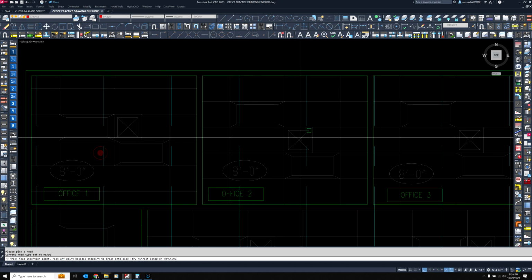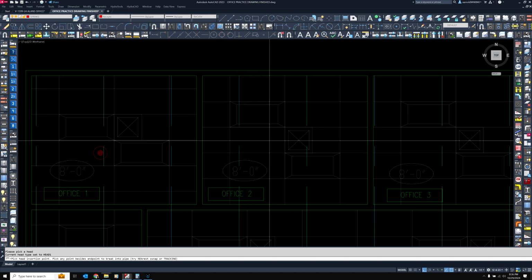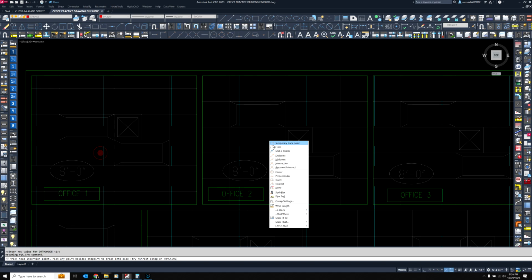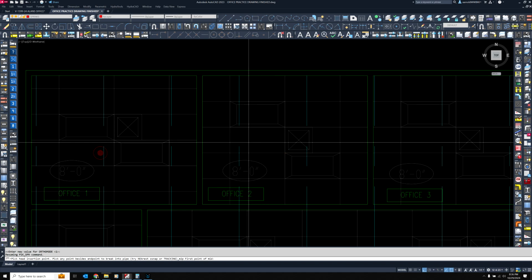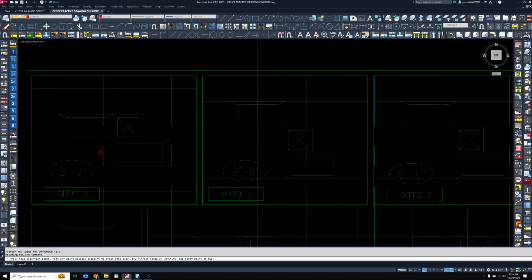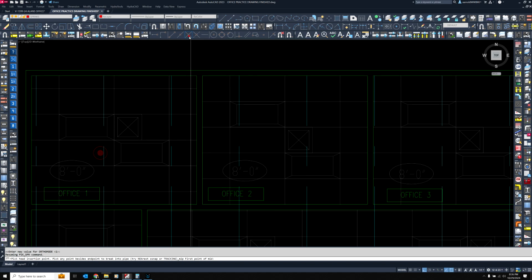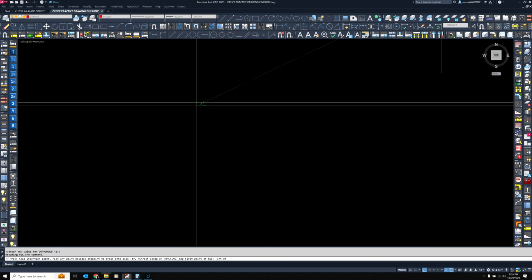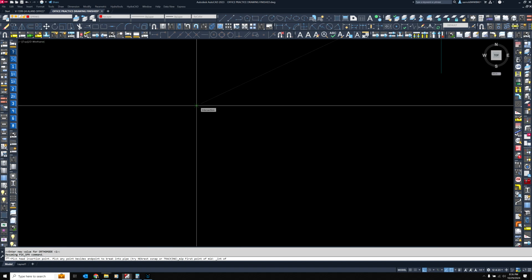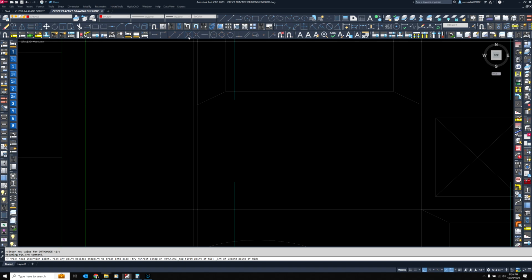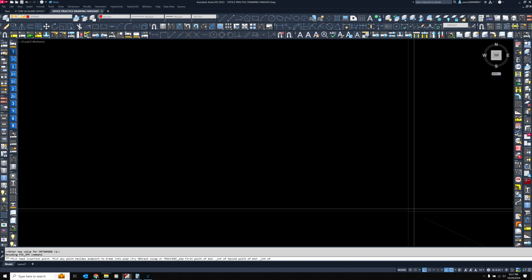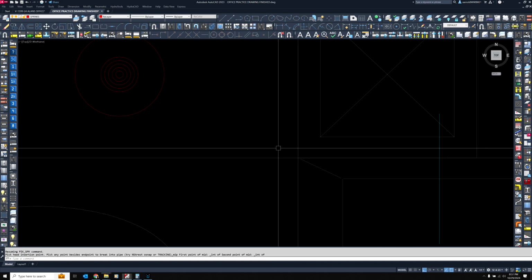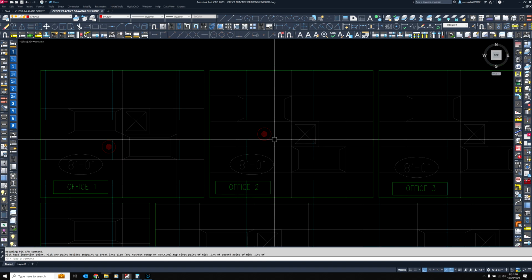And now, before I click this anywhere, I'm gonna do Shift and right click at the same time, and let's go mid 2 points. Not as useful because it's 2x4 grid, but let's just practice using the tool. Pick your intersection, and in this case we want to be real careful we don't grab that by mistake again. Where the T-bar comes together, and then specify the intersection on the other side where the T-bar comes together, and our head is in the center of that ceiling tile.